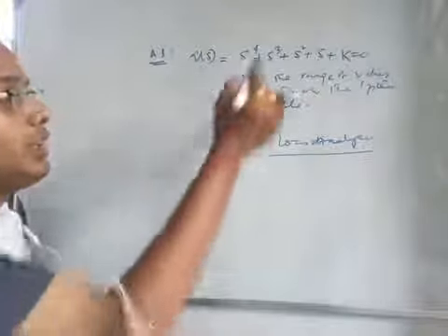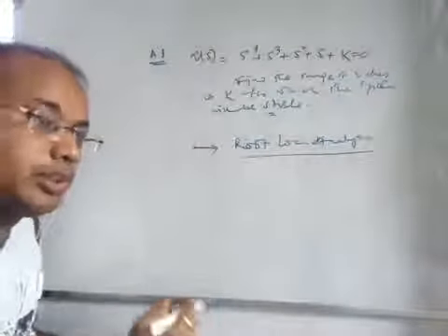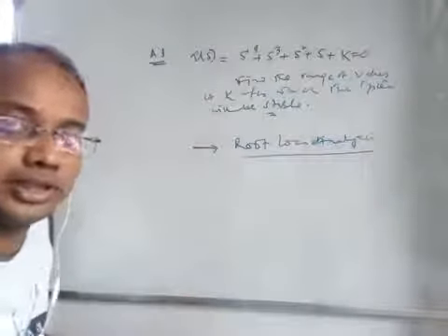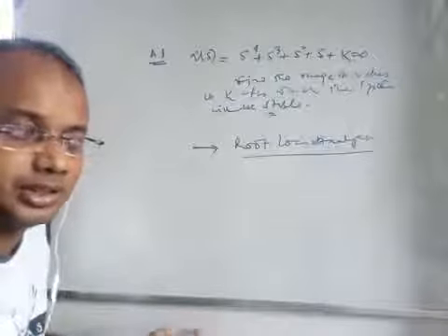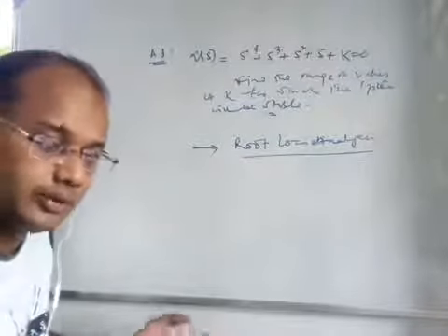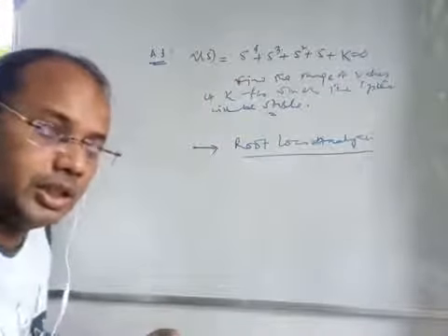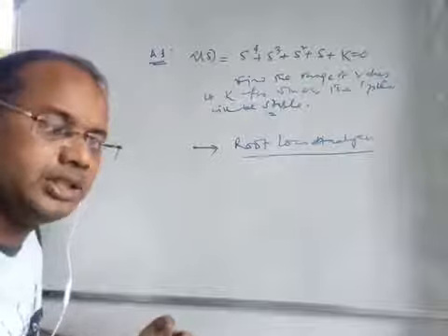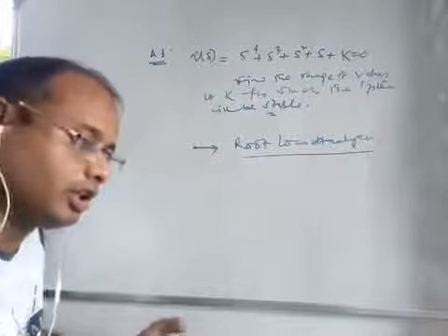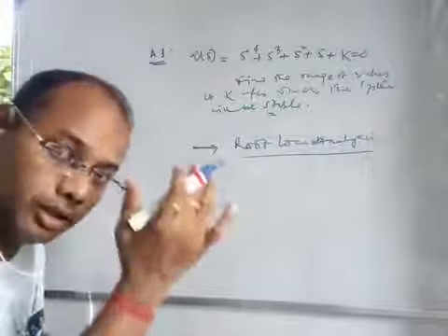So far we have discussed the characteristic equations, but the positions of the roots have not actually been discussed. It was not possible to find the roots of the characteristic polynomial using the Routh array, but we found whether the system is stable or unstable, or the number of roots on the left half of the S plane, the right half, or on the imaginary axis.